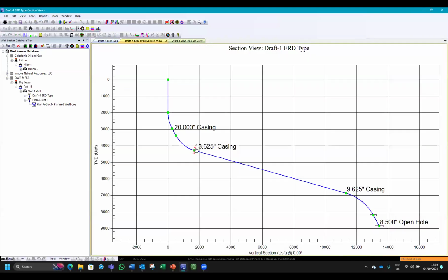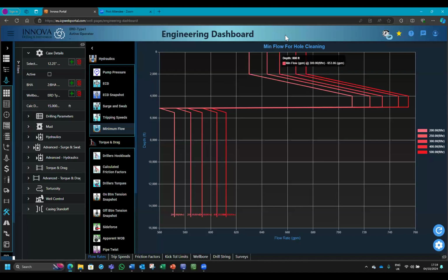For soft formation, it's something very difficult. So it's something that I want to investigate, this 17.5 inch section. I want to investigate 12.25 long tangent. Let's go for 12.25 long tangent and just see what it is telling me with the BHA I have designed or plan to use. So you can see my model.